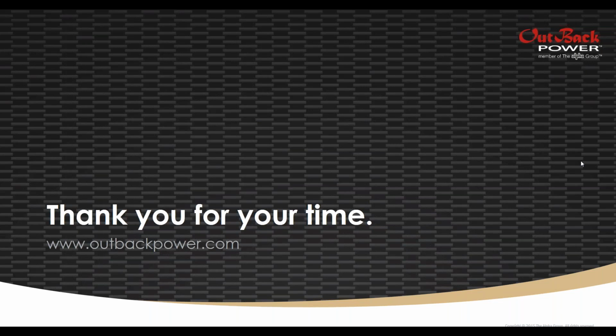Because SkyBox is transformerless, the array has to be floating, and so you need two disconnects inside the ICS Plus. So what we've done is we've reworked the ICS Plus for SkyBox and produced a SkyBox rapid shutdown solution that is a little bit less expensive than the ICS Plus. It's about 18% less expensive.